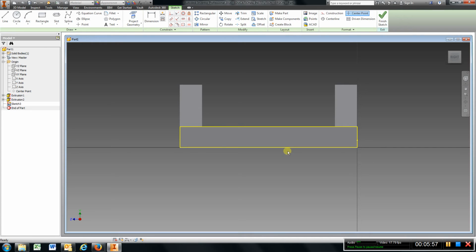and I'm going to go ahead and just draw that the way it looks. Come down, something like that. Like that. Dimension from the very top to this flat should be 1.75, enter. And this should be 3 inches because we have a 3-inch diameter boss that's going to go at the bottom.